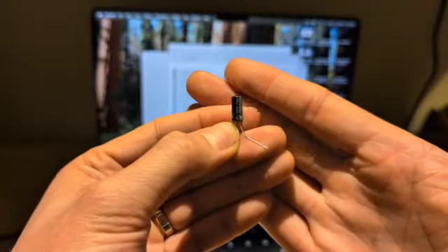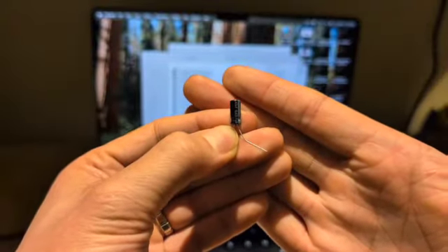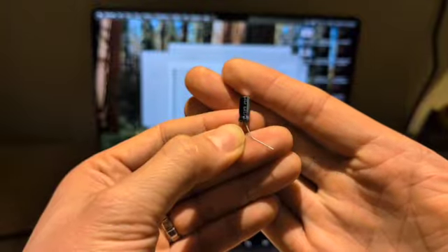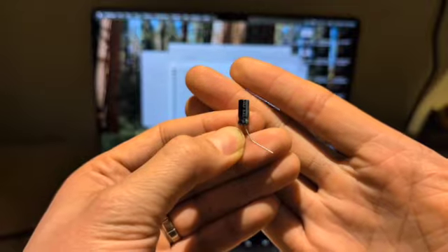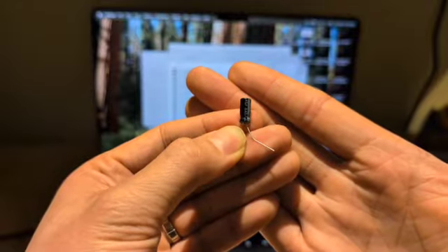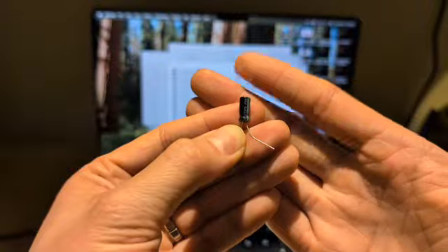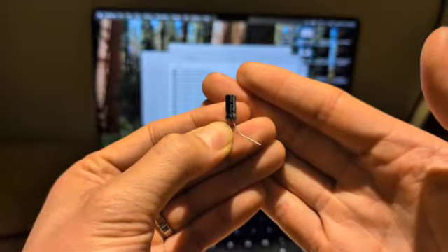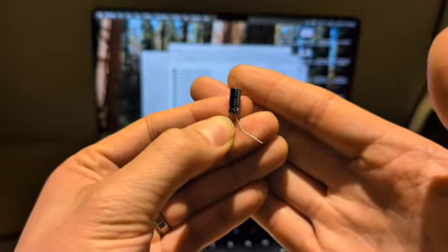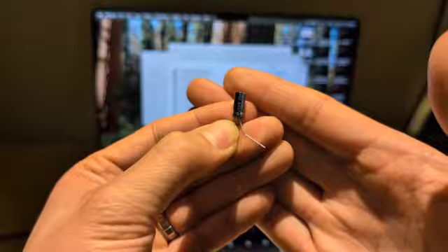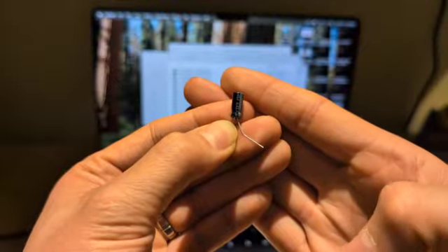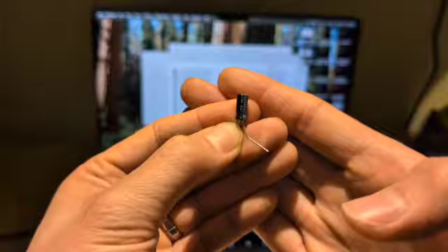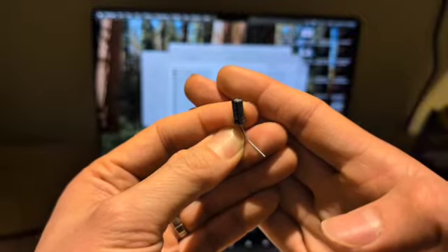Somewhere the charge is being lost. This is not a perfect world, and therefore the capacitor cannot hold its charge. Now, if it really held its charge perfectly, then you would expect the final result is that the capacitor would be charged fully to 5 volts. But like I said, because I chose such a high resistor, it's actually taking a long time for the capacitor to charge. So much time, in fact, that it's losing its charge, right? So we'll never get to 5 volts.